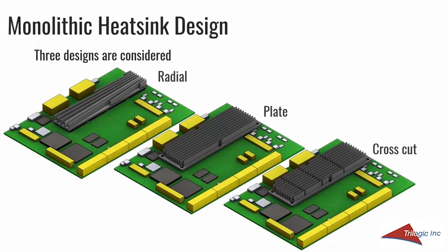Anyway, we want to look at this because coming out of Heatsink 101, people were asking, rightfully, that as flow moves down a channel, it gets to fully developed flow, and if we can have a crosscut to both maybe introduce some cooler air and also to reform the boundary layer, would we get more efficient heat transfer? We did a Q&A paper for Heatsink 101 afterwards where we explored this idea, where the sacrifice is in surface area for convection. You don't get something for nothing.